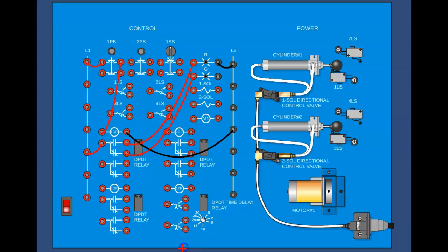Because one of these is going to our normally open and one is going to our normally closed, that means I'm taking one to the red lamp, one to the green. They should never be on at the same time. If they are, there's something amiss, because either this relay coil is energized and we're providing a path through the normally open, or it's de-energized and we're providing a path through the normally closed. So as soon as I power this on, we should see the green lamp come on, and we do. And that's because we're going through the normally closed, which is closed and providing a path for current as long as the coil is not energized.